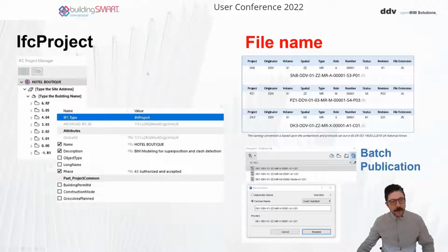Another quite interesting feature is the IFC preview feature, which in ArchiCAD is called IFC Project Manager. This means you can save a lot of time because you are able to see how your IFC model will look before exporting it. As you probably know, some of the IFC export times are quite large, depending on several reasons, but usually quite long. So it will save us a lot of time in our production activity.